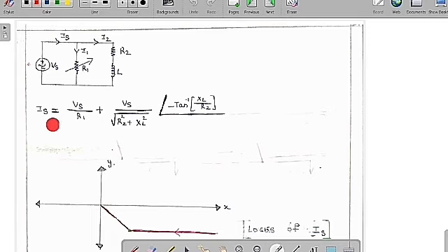So now the source current is equal to I1 plus I2, where I1 is equal to Vs by R1 and I2 is equal to Vs by R2 plus jXL. If you want to convert it to polar format, it finally becomes Vs by square root of R2 squared plus XL squared at an angle of minus tan inverse XL by R2. So for this we are going to draw: when R1 varies from 0 to infinity, what is the nature of the source current we are going to figure out.